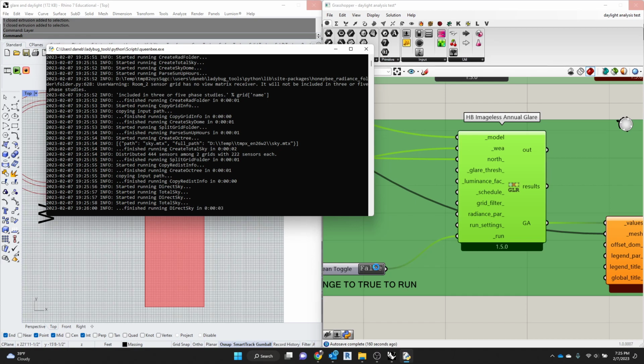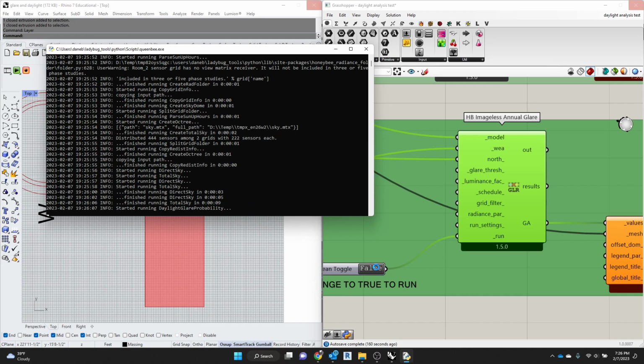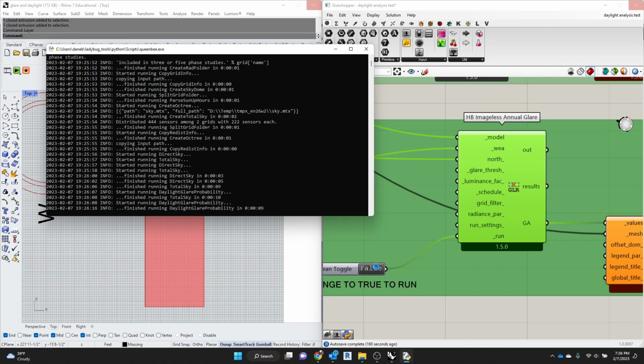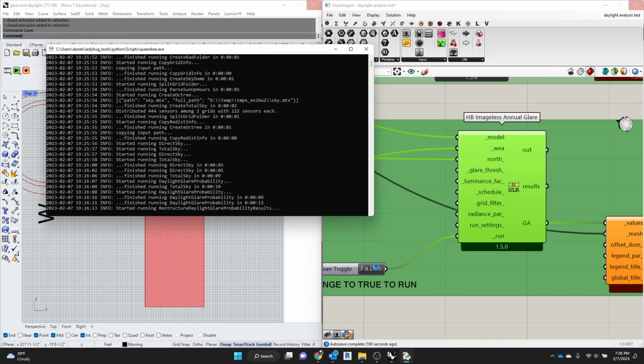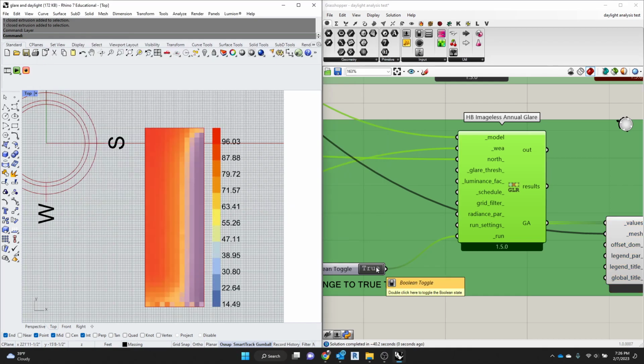because I feel like you're all going to go to the Heliodon and put windows on your building, and then you're going to realize, oh, I'm not getting a lot of light deep in my building, so I'm going to make bigger, wider windows. But there are downsides to those things. You can have windows that face south. Think of a skyscraper that has no shades on it and does not produce glare. Does anybody know why? Not necessarily special glass, but yes, a different kind of glass. A tinted glass will prevent glare from coming off those windows.